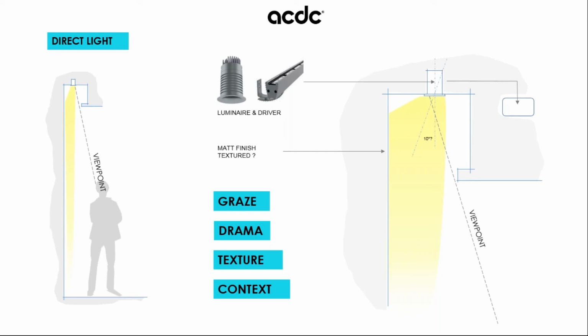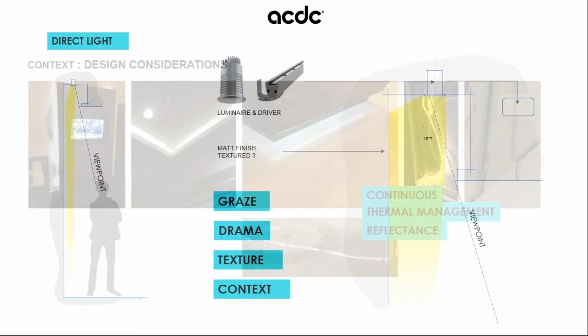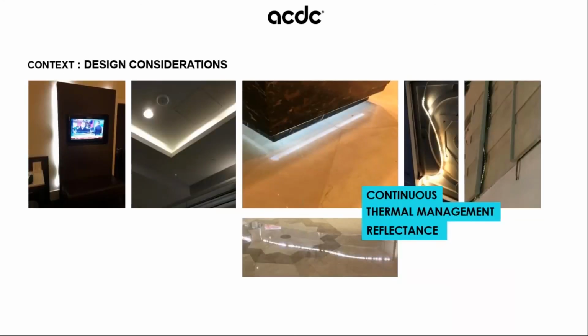One thing I would really just consider is, what do you want this to look like? Okay, so when I talked there about reflexes and finishes of the materials that you're working with, get an understanding of the context where your project is. So what we're trying to make sure is that the lit effect goes right into the corner, that it's a diffused lit effect, that it's going to be there for the long term, that there aren't shadow gaps between luminaires.